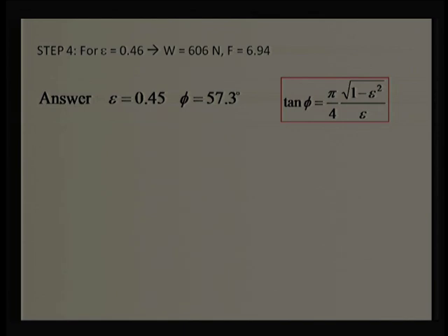It is as if we have capabilities, but we are not giving our best performance. The bearing has a lot of capabilities, but because of the larger length, it is not able to give its best, which is not desirable. First, going for a larger bearing length naturally increases the cost of manufacturing and the cost of the material. In addition, there will be some misalignment. In addition, there will be additional friction force, but we need to check it.